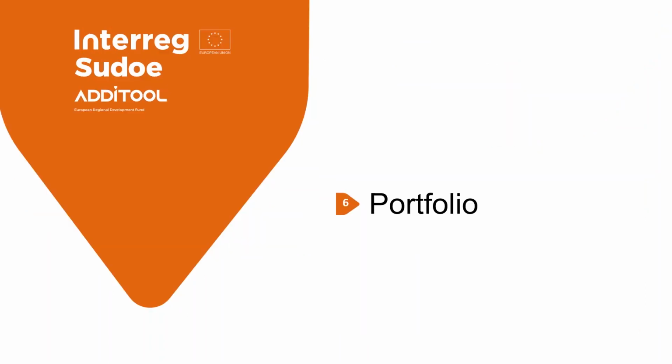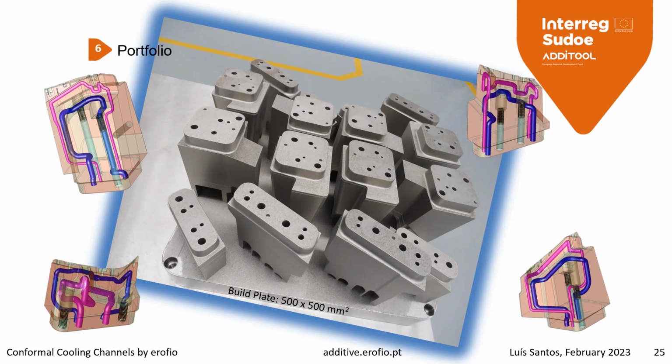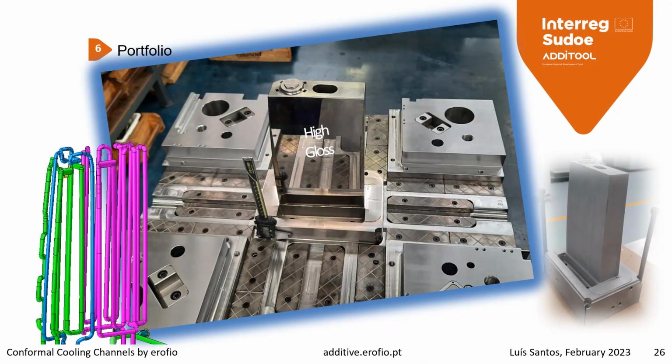And these are some examples of our build jobs. Like you can see, it's a build plate of 500 millimeters square. And here you have some examples of the cooling channels of some of the parts that are on this build plate. We can have all kinds of shapes according to the needs. We can have parallel cooling strategies or serial cooling.